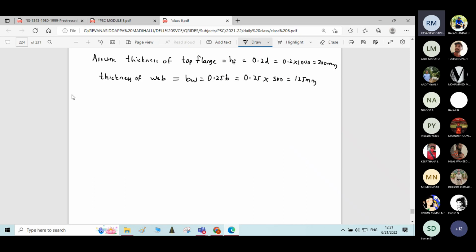Okay, here you write that sentence, assuming neutral axis depth XU is equal to depth of flange only, or height of flange only, as 200 mm. Which will fall under case 1 only. Neutral axis lies within flange. It will fall under case 1 only.